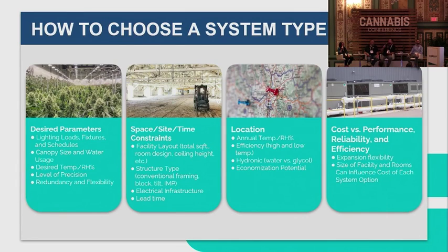Yeah, it might make sense to describe what economizing is first. Yeah. Go ahead. It's free cooling without using a compressor. Yeah, free cooling without using the compressor, so you can either get an integrated chiller with a free cooling option, or you can have a separate unit entirely. It's just fans, where you divert the water through the fans when it's below the temperature of the coil itself, and then it may need to supplement. So it makes sense to look at the trade-off. Below freezing quite a bit of the winter time is a good option to look at.